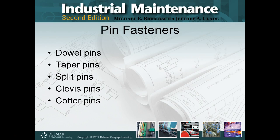Clevis pins, nothing more than a nice straight shaft or shank. You've got a flat or round head on one end, and on the other end, drilled perpendicular to the shaft, is a hole which a retaining clip goes through. Or a cotter pin. A cotter pin looks like a hairpin, usually made with either flat, half round, or round metal stock, and it looks like a hairpin with a nice bulbous end, and then I call them legs.